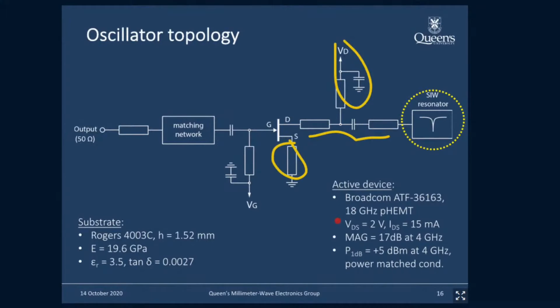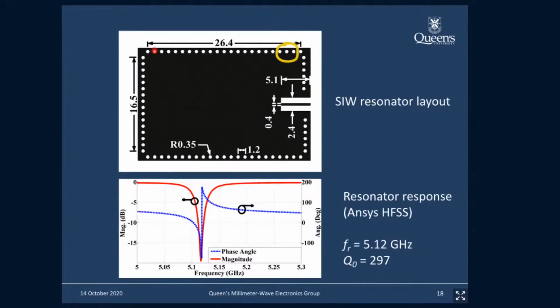Now, with these substrate integrated waveguides, what you're trying to do is replicate the rectangular waveguide on a printed circuit board. And the way you do that is that you put via holes between the top layer of the board and the bottom layer, and you plate through the vias. And if the vias are spaced closely enough, then as you know from basic electromagnetics, this will actually look like a solid wall to the wave propagating in the structure, right?